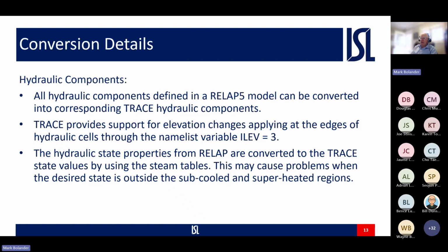The hydraulic state properties from RELAP are converted to the TRACE state values using the steam tables that are in SNAP. This may cause some problems when the desired state is outside the subcooled and superheated regions. So be wary of that.